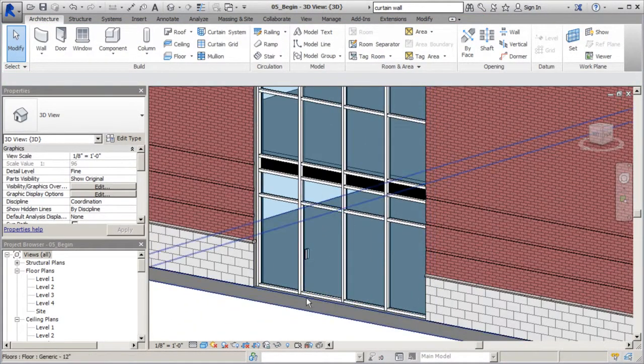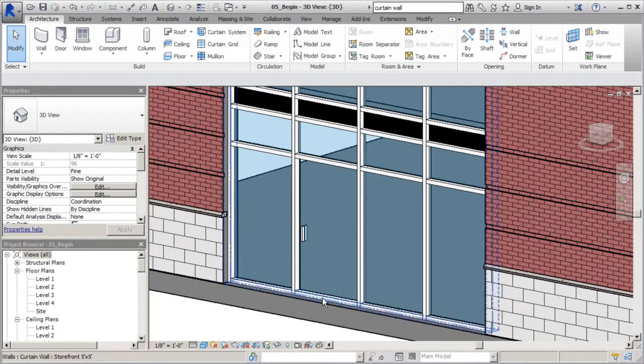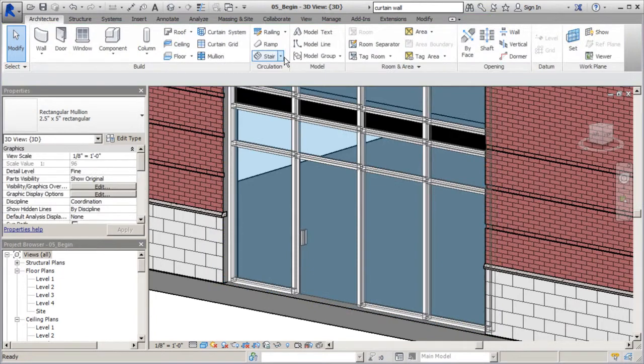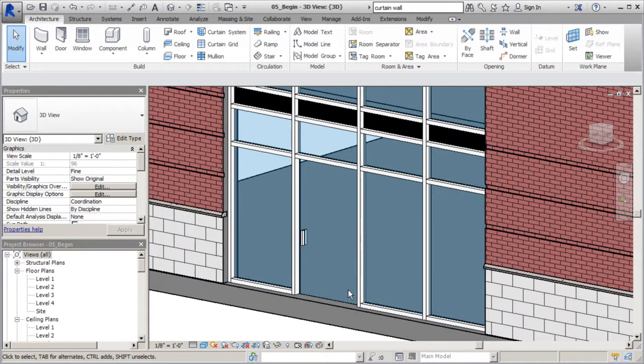And we're not done yet. We still have this bottom little trip hazard here, this mullion at the bottom. So I'm going to tab here. I don't want anybody to trip getting into this building, so I'm going to select it, unpin it, delete it, and now we have a door in place. Again, depending on the size of your door, you can adjust by playing with your grids and manipulate like we did when we moved it up. Do the exact same thing with the vertical ones. So we have our door in place.